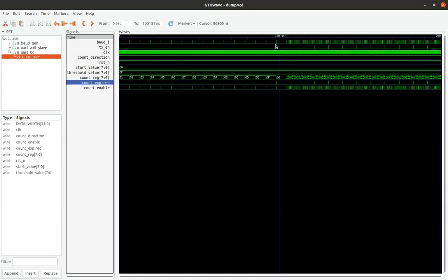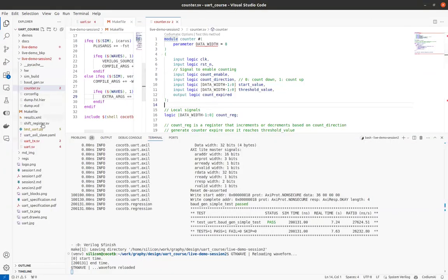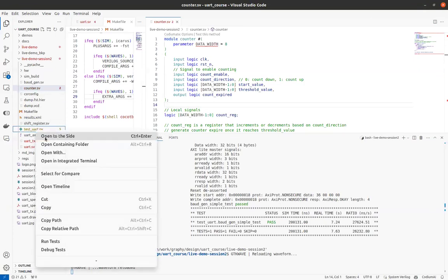So in this entire signal we got only one pulse, that means one bit period. It is roughly around 100 microseconds. But later in the test we are increasing the baud rate by configuring the baud. We can go back to the test and see what we programmed.